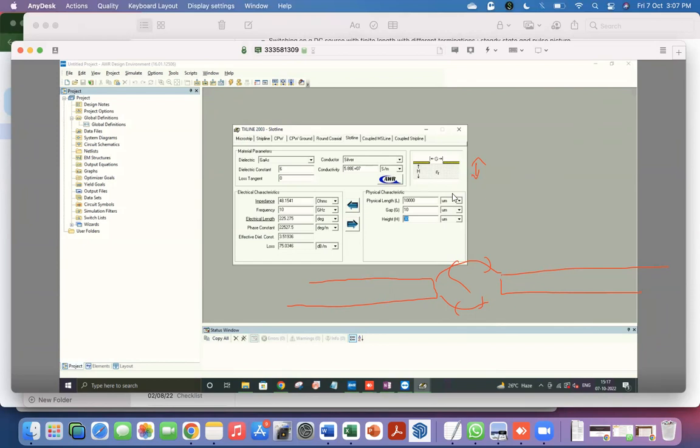If that dielectric is very thin and there's something else, then it will start feeling that, which could just be the absence of a dielectric, which means there is air on this side, or if you have a metal plane. Obviously in the ideal slot line, there is no metal in that model, but you could have a metal there, but then it's no longer a simple slot line. And I'll show you an example which will explain this in just a little bit.